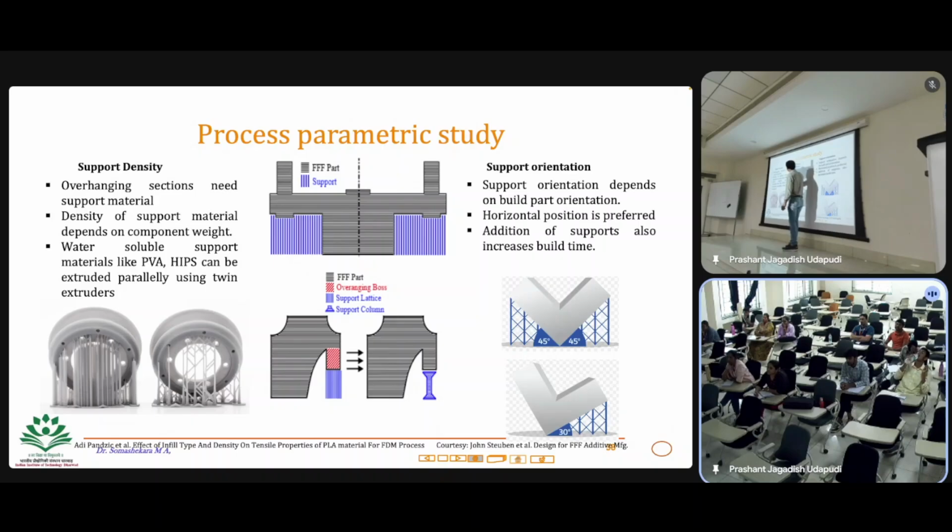Because without this, you cannot print, because it is almost like a 90-degree angle. Before you start the printing, you will be able to print to some extent, maybe partially. You can extend a little bit of support structure from the modeled material up to maybe here. But if you go further, the material will simply fall. But you can take advantage of the previous layers.